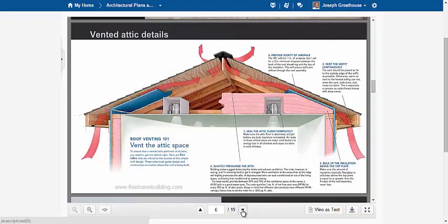This next picture is probably one of the hardest for people to really understand, and quite honestly, it's one of the dumbest designs we've come up with, in my opinion. It's so hard to regulate ventilation in attics. If you've been up in the attic in the summertime, it's just boiling hot, 100 and some odd degrees up there. What's supposed to happen is that cooler air comes in through what's called our soffits here, comes up inside that attic through natural ventilation, because hot air is supposed to rise quicker than colder air and vent out of the top.